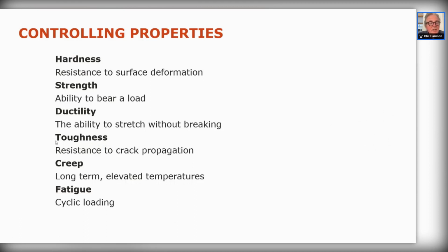But it is mainly classed as an elevated temperature process. It is also a function of the melting point of the material. It becomes significant above about 0.3 of the melting point of the material in degrees absolute. So the higher the melting point of the material, the better the creep strength at elevated temperatures.